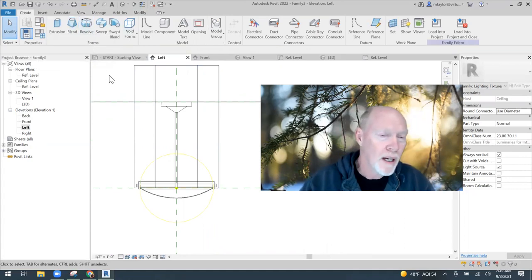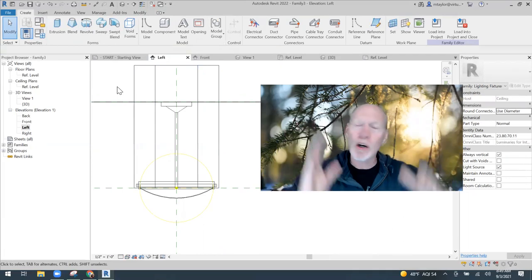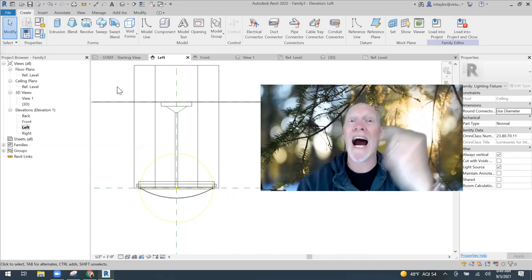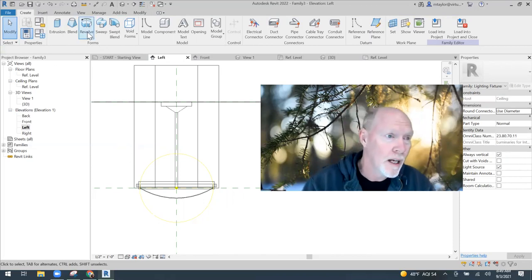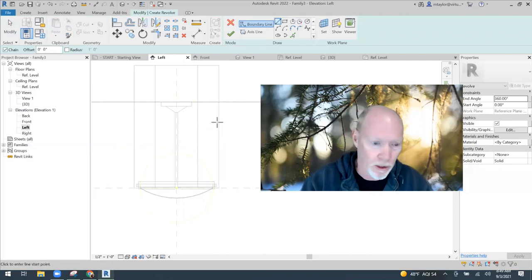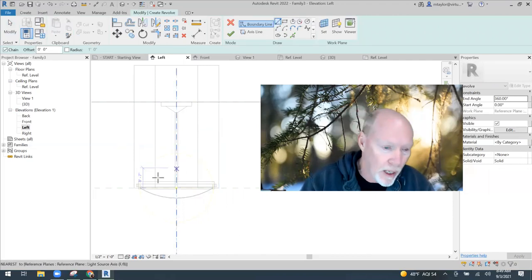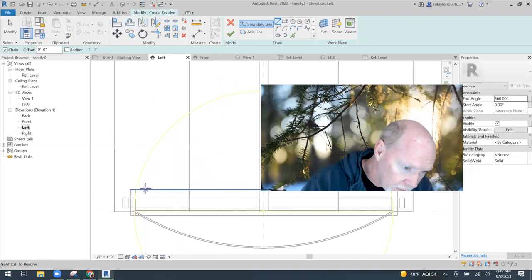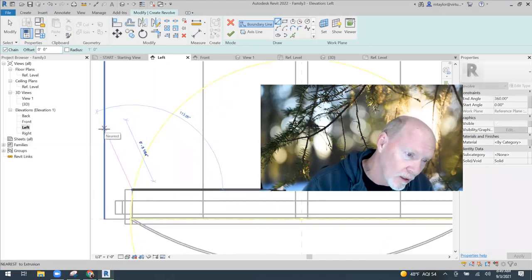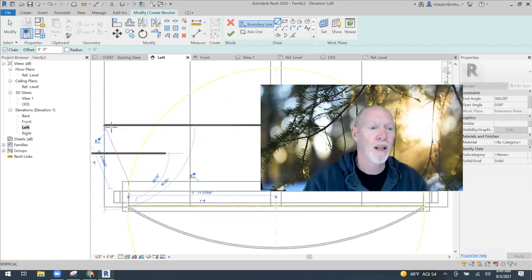Just work with me. I do that because if you start with a void, it starts cutting things immediately, and I don't want it to cut anything but what I tell it to cut. So look at this. I'm going to make another revolve, and this is going to be my pencil sharpener, okay? I am going to make a pencil sharpener from right here. I want to cut up at that angle. That looks like a good angle for this thing to be at, okay?